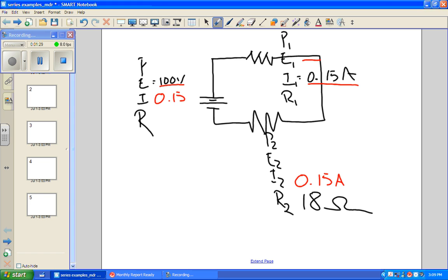If we were given a voltage in one of these, we can subtract that from the supplied voltage and find the, let's say we had 3 given voltages and 3 resistors, and we were missing the 4th voltage, and we had a supplied voltage. We can subtract the existing resistor voltage drops from the total voltage drop and find our voltage drop across that one resistor. But this is not the problem I was looking at that had that in it, I guess, but that's okay too.